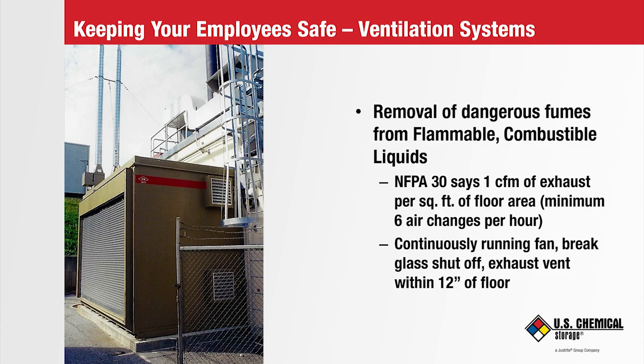During a spill, flammable combustible liquids will flow down through the elevated floor to the bottom of a flat sump floor, spreading evenly all over the building. This provides the greatest surface area for evaporation, which will create the fume. Immediately after a spill, the liquid is exposed to the air, even before the liquid hits the floor. It evaporates and becomes a fume or vapor.